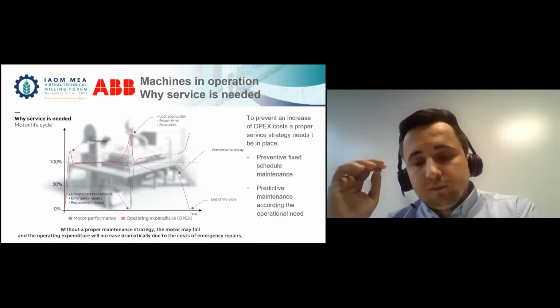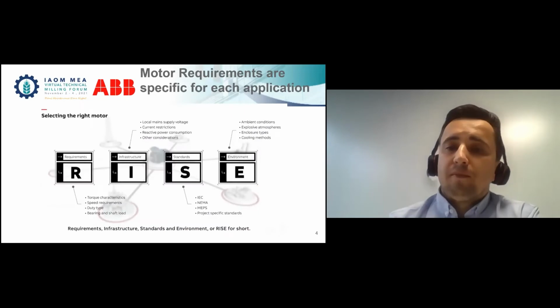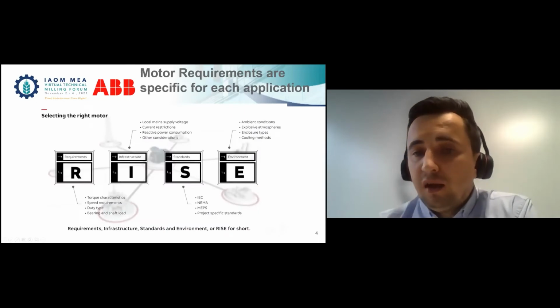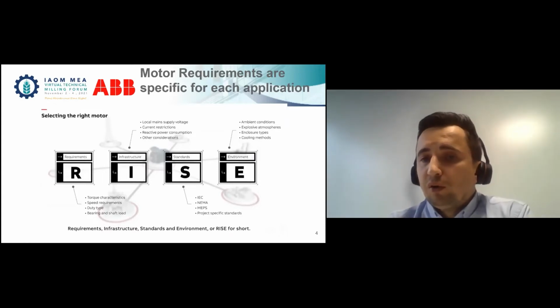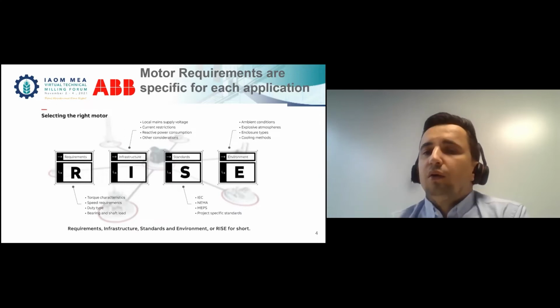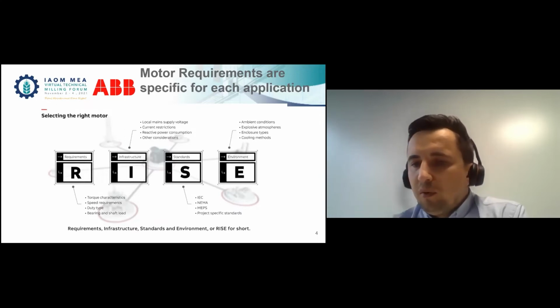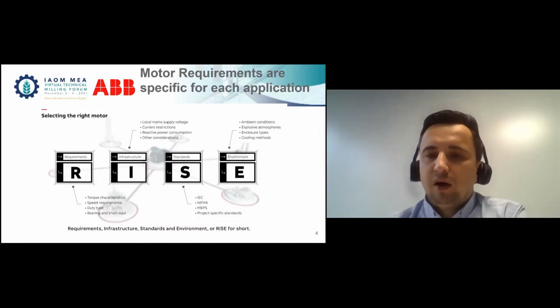So we are now coming back to this topic, why service is needed. One other thing is exactly this environment, to come back to the specification environment, like hazardous area or enclosure types and ambient conditions. So if you buy a motor from stock, and you have maybe 50 or 60 degrees in your application, then this motor maybe will break down earlier or will not be able to deliver the required power, because the standard motors are designed to be operating at 40 degrees Celsius environments, as an example.